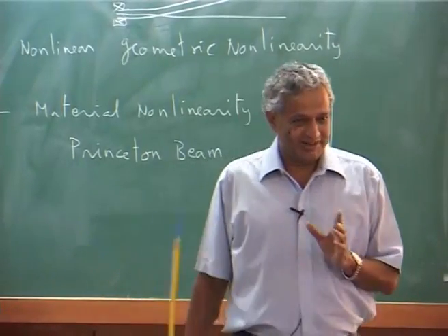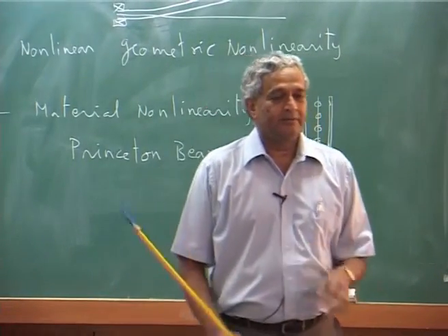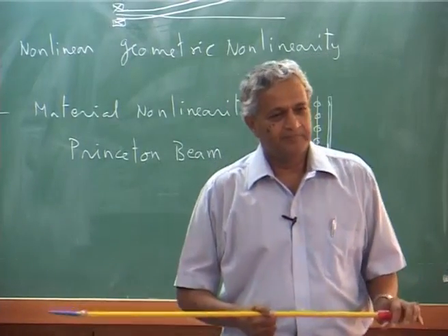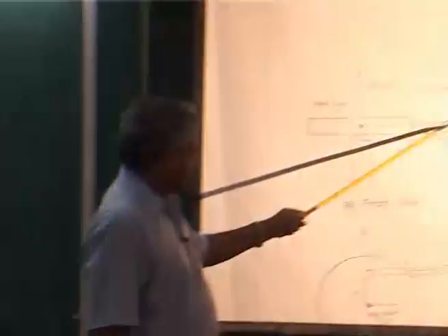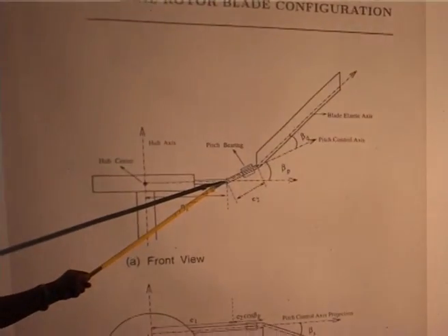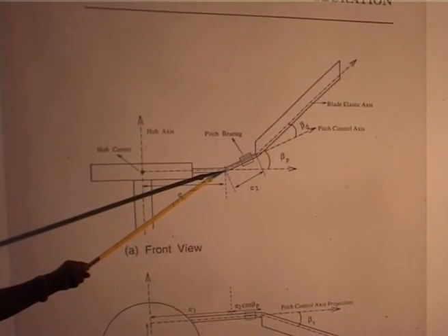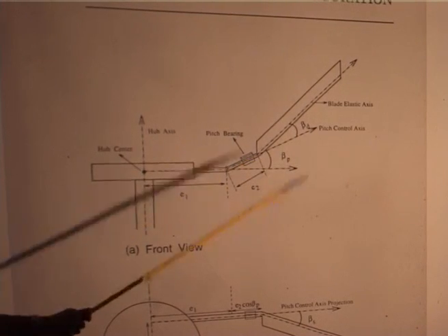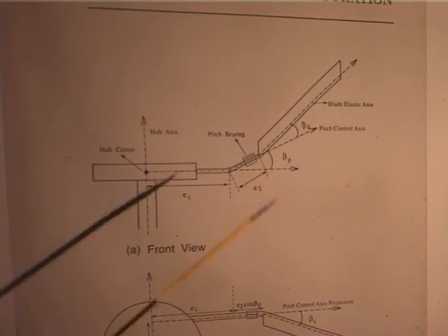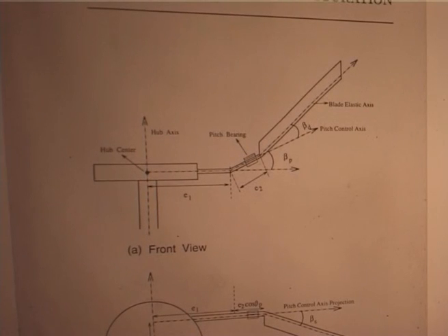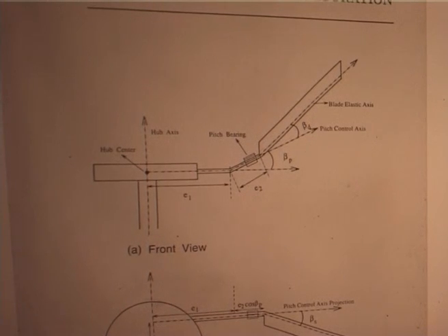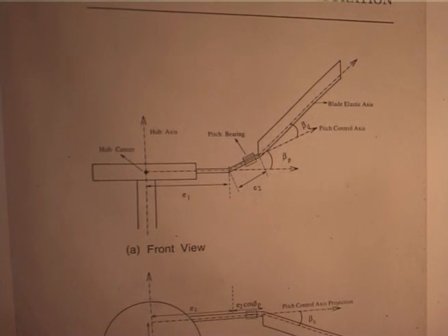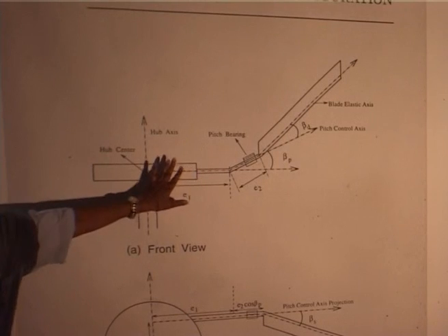So, you got it. But my doubt was where the pitch bearing is, where we are giving a Precone angle, that point, that's a hinge, right? No, there is no hinge. Flap hinges? There is no hinge in these things. Okay. This is the hingeless blade configuration I have shown. If you have a specific flap hinge, that we will come to. That is where I said, this is just a configuration, I have not shown actual geometry.